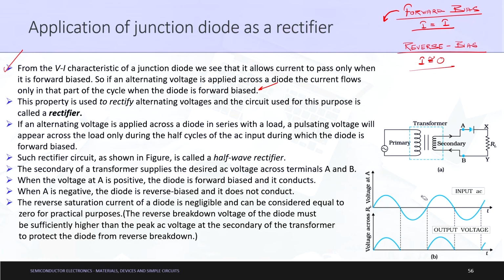Either we can change the semiconductor diode, or we can change the battery, correct. So, what is basically happening is, if the battery is providing a potential of V in one sense, it is providing a minus V in another sense. What does it mean? Let us say we apply an alternating voltage. Then in the first half cycle, it can be said to be forward biasing because a plus V is being applied there. In the second half, we are doing a reverse biasing because minus V is applied there.